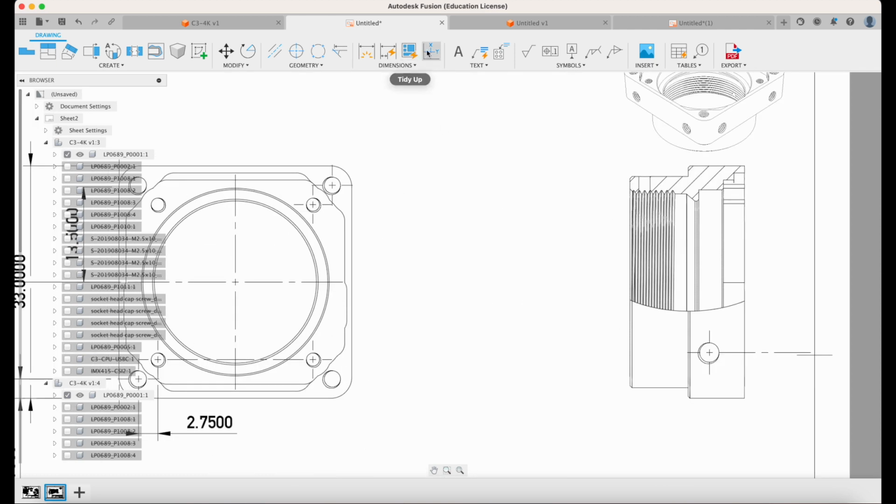But the next one is very important, especially for manufacturing from these pictures. Okay, what we have is the ordinate dimension. Now the ordinate dimension is what we call a datum point, which is the reference dimension from where everything goes incremental.